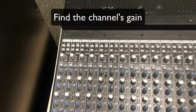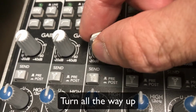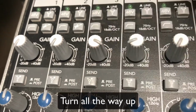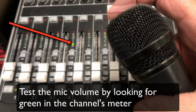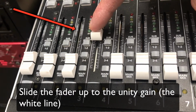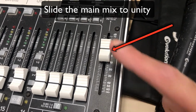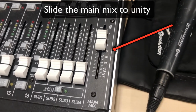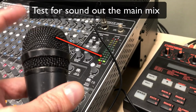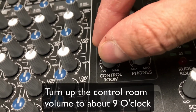If there's no open slot, you can just take something out and plug it in. Once you've done that, find the gain for the channel, turn it up all the way, then test the microphone volume with the metering. You're going to need to slide up the fader then to unity, and then slide it up on the main out as well. Finally, test the microphone output volume going out of the main mix, and turn up the control room volume to something around 9 o'clock.